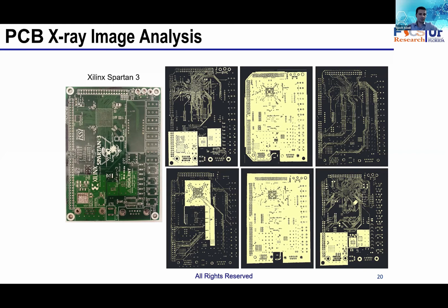So all the soldering material, all the capacitors with lead in them, the ports with all those leads, they are going to attenuate the X-ray, and that is going to cause noise when the 3D image is being reconstructed. So this work that we did back then was on an unpopulated board. So as soon as the board is getting populated, the challenge comes in.